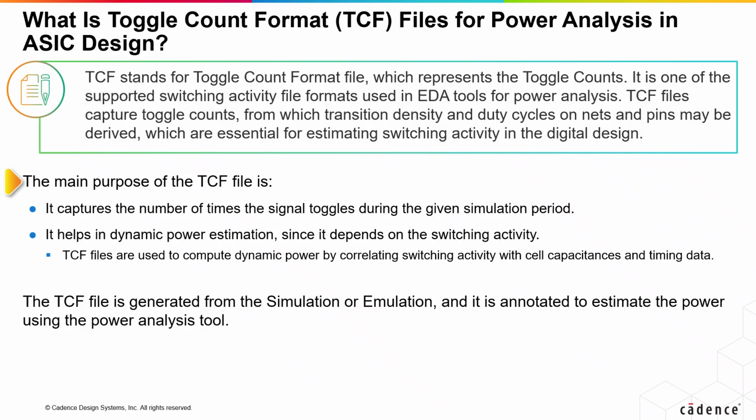Along with toggle counts, TCF files also record transition probability, or duty cycle, which indicates how long a signal stays at logic high versus logic low. This information is critical because both switching frequency and signal probability influence the charging and discharging of capacitances in CMOS circuits. TCF plays a crucial role in dynamic power estimation, as dynamic power is proportional to switching activity, capacitance, and